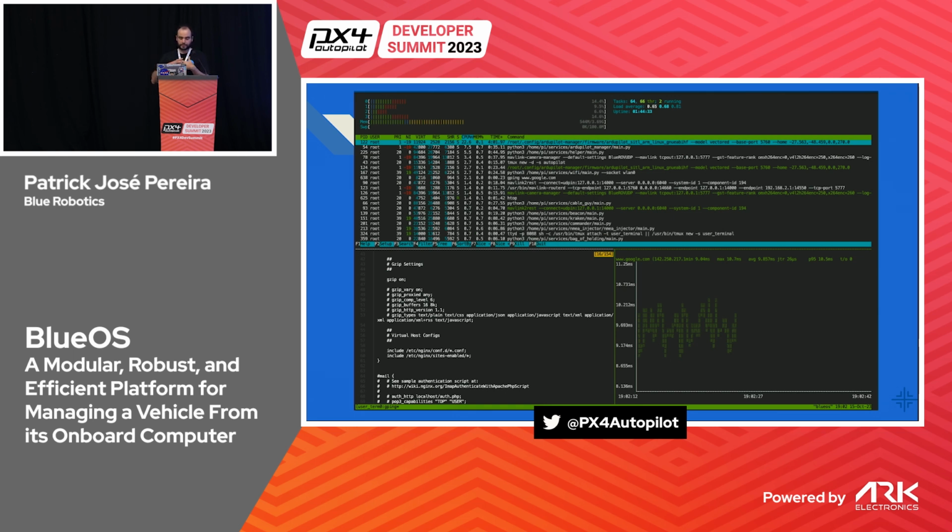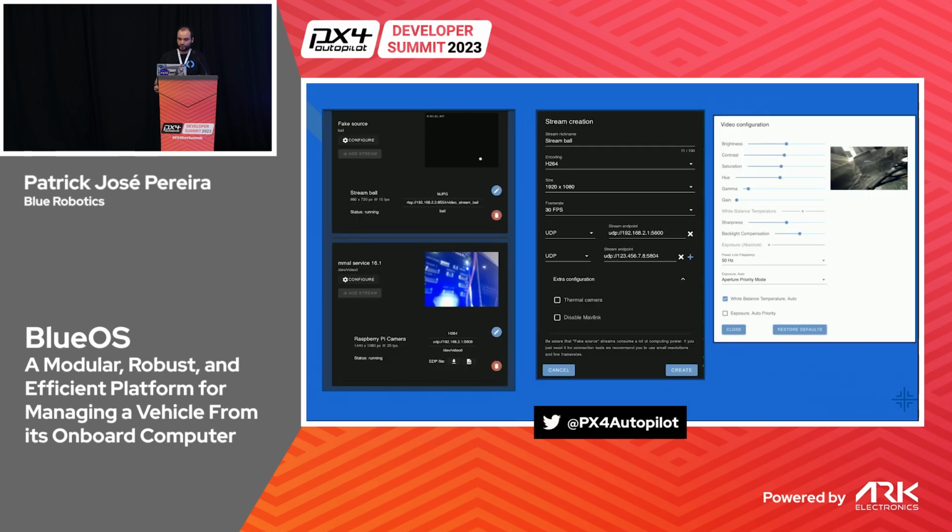We have a bunch of binaries to help developers, i2c-tools, bat, mtr, and everything that a user for debugging and development should care about. But by default, we use the Mavlink Camera Manager to do all the video bridge from the companion computer to the Surface computer. In this case, we have a fake video stream and a connection with the Raspberry camera, one using RTSP and the other UDP. By default, the camera manager also creates video streams that display via WebRTC.